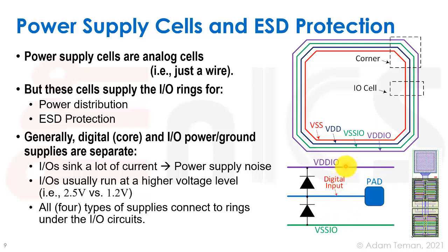But that is in case we want an analog IO that has an analog voltage between VSS and VDD. What if we want a higher voltage or a lower voltage going through the analog IO? Then we cannot actually connect them to these. So you'll have cases where you'll have analog IOs that will not have ESD protection. And what you should do is add one of these clamps. Usually there's going to be an IO clamp in the library to connect it to at least the voltage that you're not going to pass, or to protect it with the highest or lowest voltage you're going to ever reach.